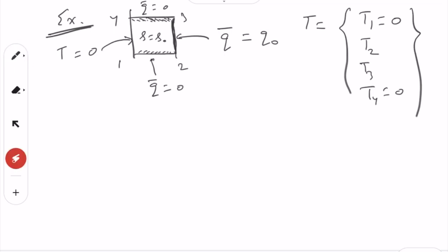So now this is a force, or this is a body force which is given here, and finally you know that all the calculations are done on these nodes only. So although S is distributed, this heat gain is distributed everywhere, we have to put this total value on these nodes only. And if you are experienced, or if you have insight into it, you automatically know that in this case from body source the total will be